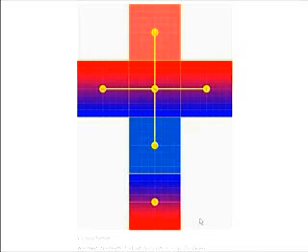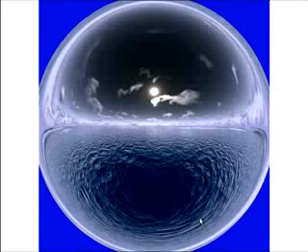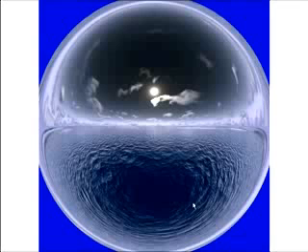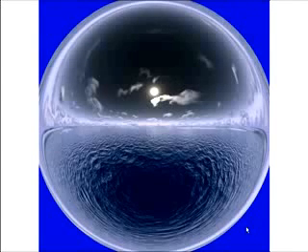Another very common type of mapping is the angular mapping type, also known as the light probe. And here's an example of a light probe image, and all it is a square with a circular area that contains all the HDRI information. So the area outside the circle doesn't contain any information at all, or at least any additional information other than what you see in the image here.